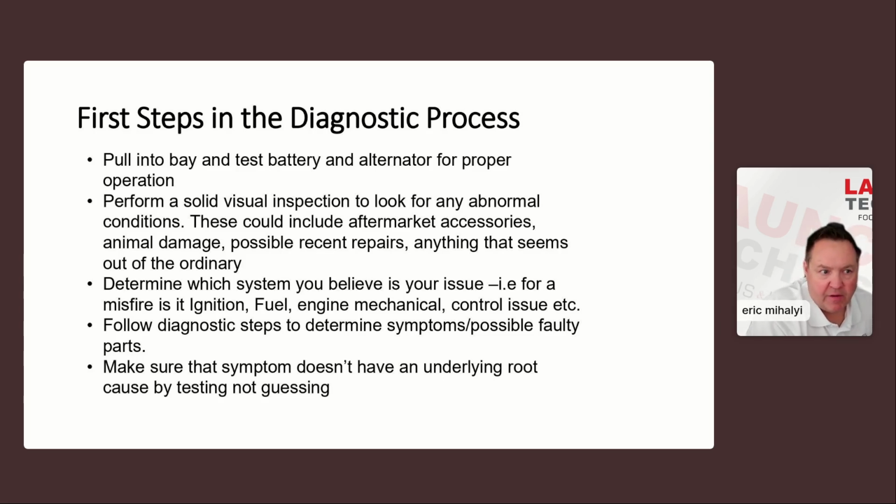But what's happening is, if you've got that bad diode and you just do a charging system alternator test, yeah, you might see that you're getting X number of amps. It's going up to 14 volts when the alternator's running. You think everything's great, but you're not checking for that AC ripple. That AC comes out and it can slowly, especially if it's a regular lead acid battery, boil some of the water out of it, and then it slowly kills that battery. So it's really important that you do those two things.